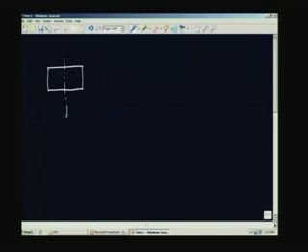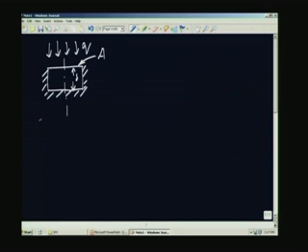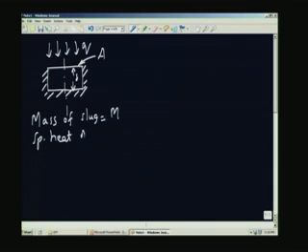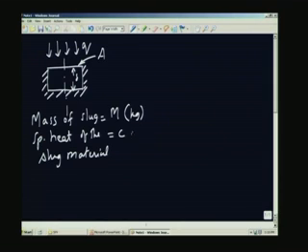So, we can assume that it is more or less well insulated on the sides, and we have a certain thickness delta, and then we have the Q, which is coming in at the top surface, and the area of this surface is A. So, the slug has a mass of slug equal to m, and the specific heat of the slug material is C. So, this will be so many kilograms, and this will be in joules per kilogram degrees Celsius.